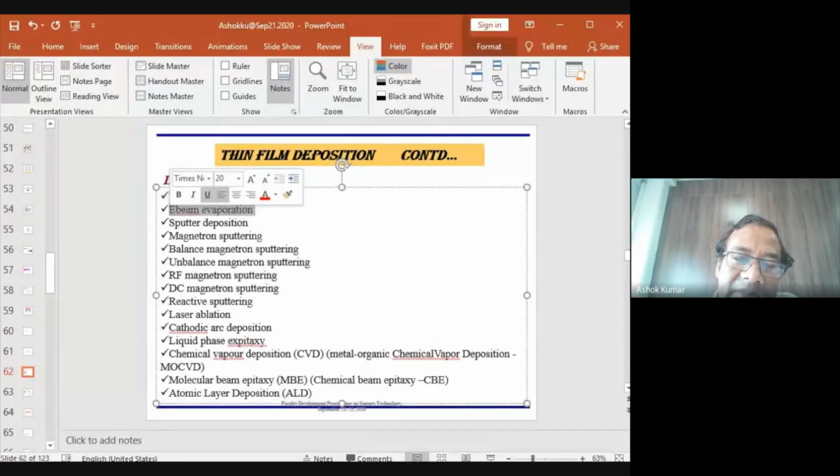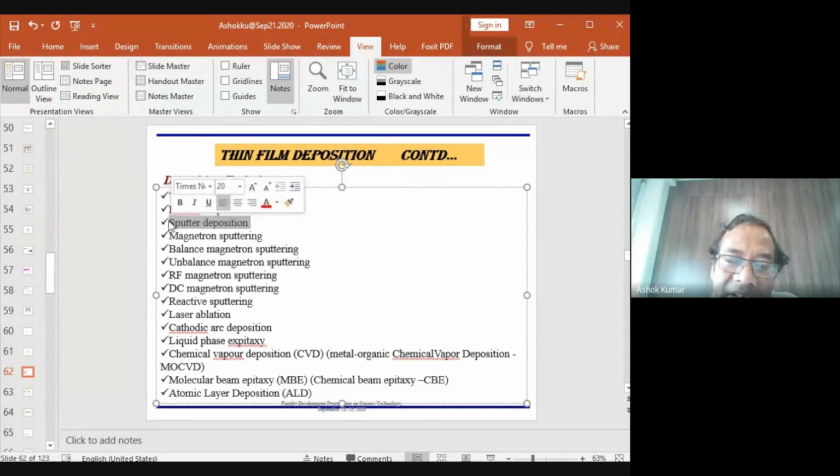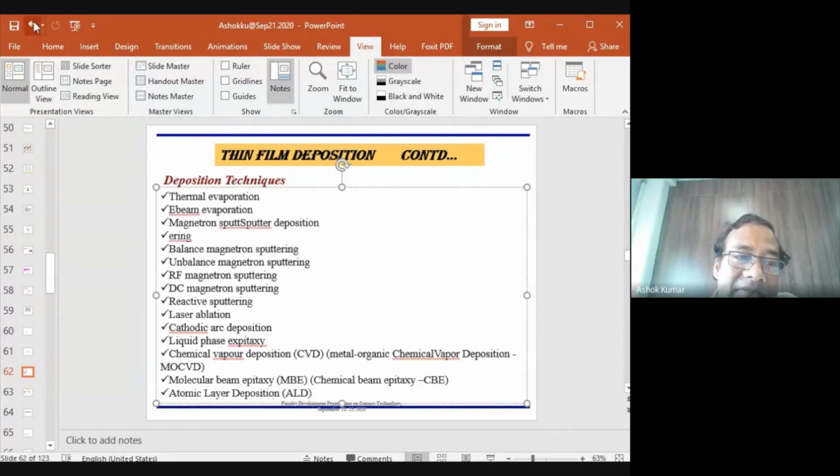So that means in the E-beam evaporated thin film, atoms and molecules are arranged in systematic and periodic order. That is the crystal. And in sputtering, they are not arranged in systematic and periodic order. Normally, they become amorphous, because the deposition rate is high in sputtering. And you can simply consider this with the students in the class.